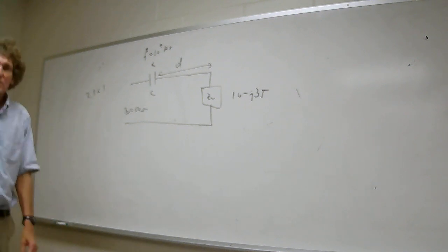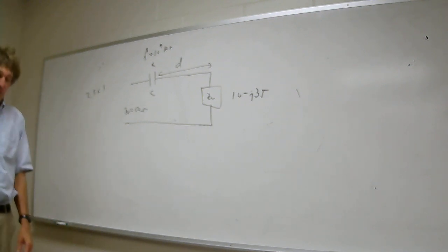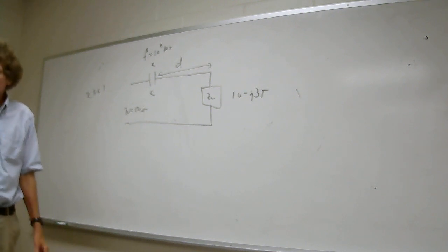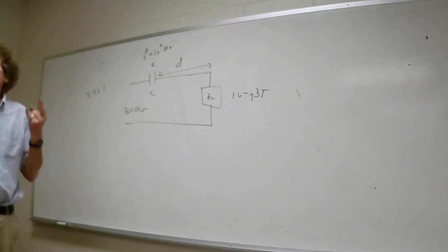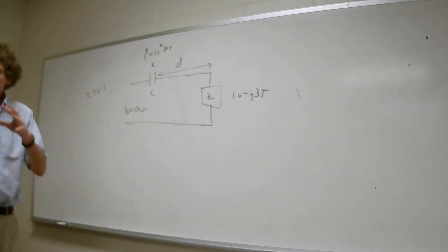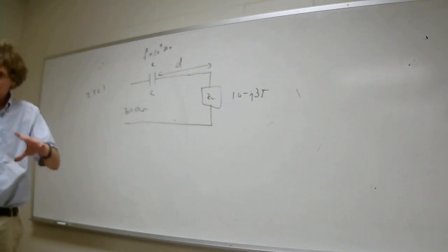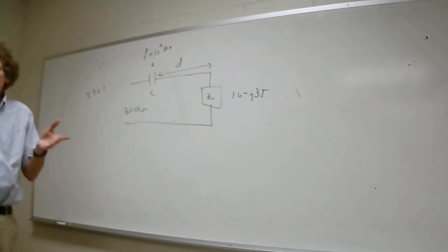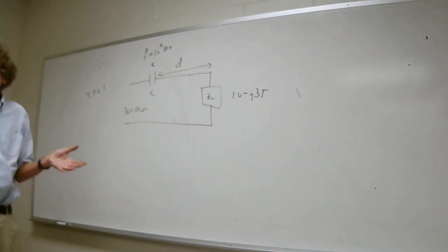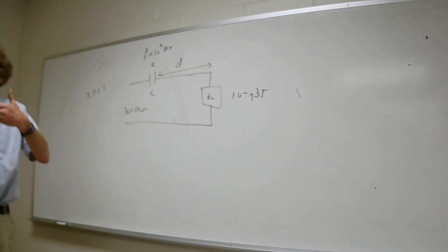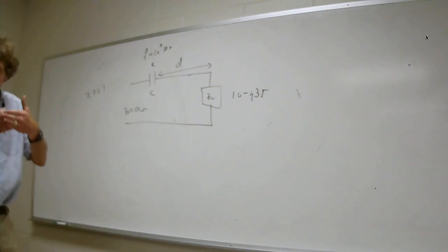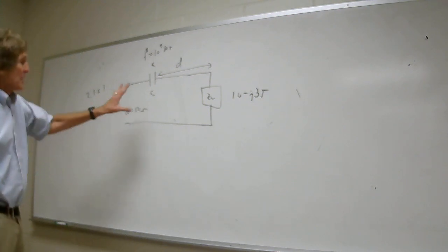With analog electronics, you'll find that anytime you have bipolar transistors, did you have transistors at all yet? In digital electronics. Well, if you have any type of bipolar, not FET, but bipolar, you have to have a DC bias current to set the quiescent point, right? For FETs, you don't need that because it's basically a capacitor. It's the gate that prevents it. Okay. Anyway, back to this problem.